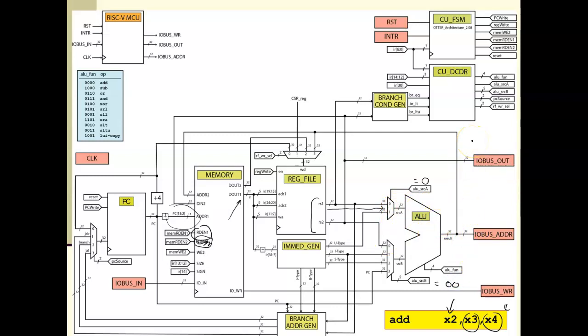ALU is a combinatorial circuit. Data feeds around here, and you need to get that data back to the register file. And so here comes the result. It's coming around here, and it's going into this mux right here. So RF, this value right here, needs to be 3 to get that data in here, and then inside the reg file I need to turn this write on, so this needs to equal 1.